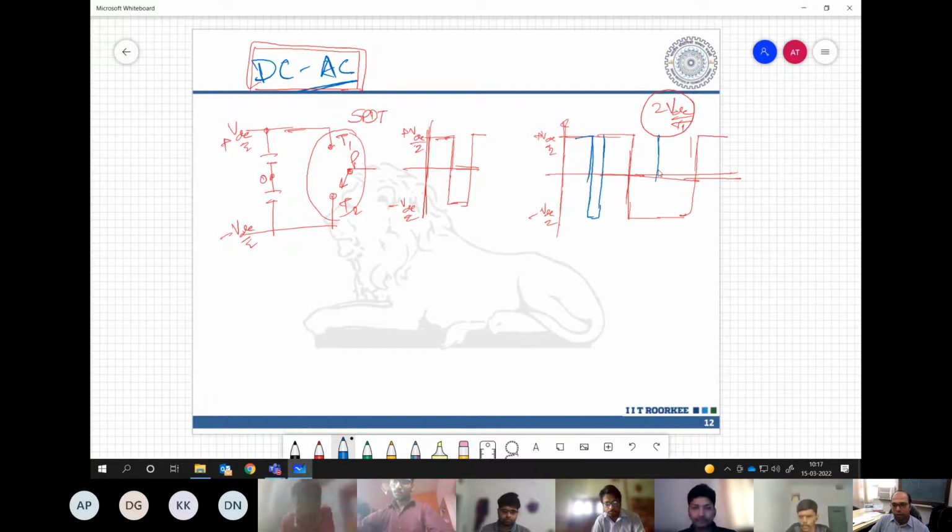By maintaining waveform symmetries, several harmonics can be eliminated and the phase for the fundamental and the harmonic components can be defined properly if you have all the four symmetries, which means the full wave symmetry, half wave symmetry, quarter wave symmetry, and if you have a three-phase system, then three-phase symmetry. So by this we are able to eliminate a lot of harmonics and maintain the phase of the components properly. This is what we do.